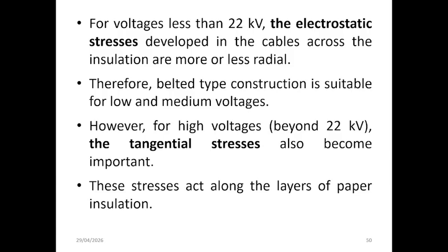Okay, this slide explains why belted cables are suitable only for lower voltage levels. For voltages below 22 kilovolt, the electrostatic stress in the cable insulation is mainly radial, making the belted construction adequate.